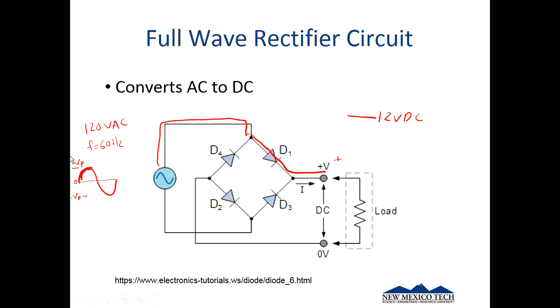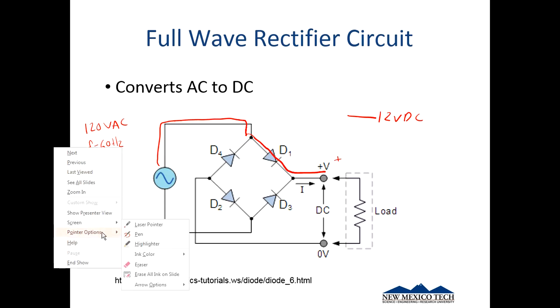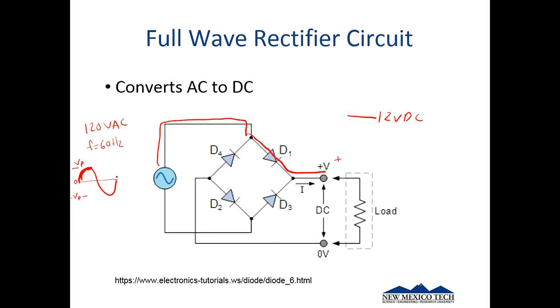Now we switch gears, and let's look at what happens on the negative stroke. So now we have current flowing this way. These two right here aren't connected, so we just kind of go through. And we get to here. Well, current can't flow back towards D2 because it's a diode and won't let it travel that direction.